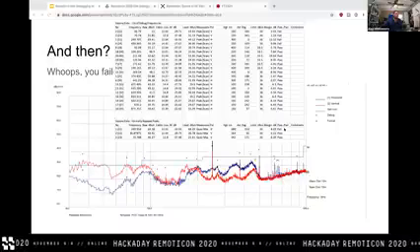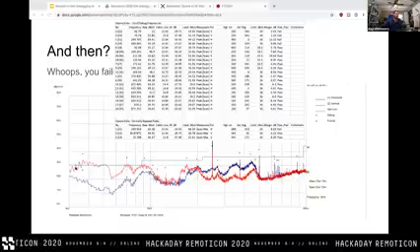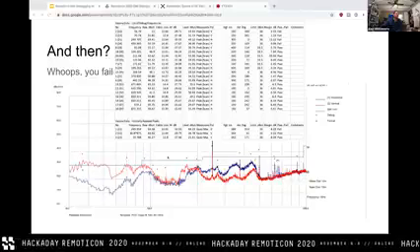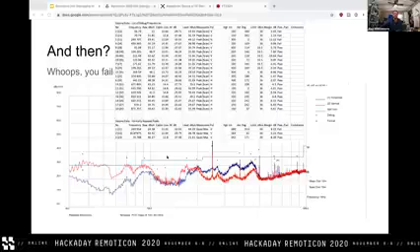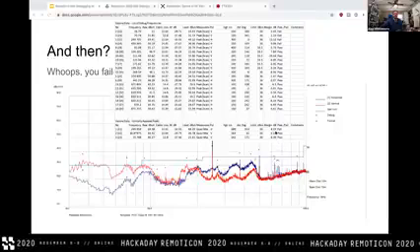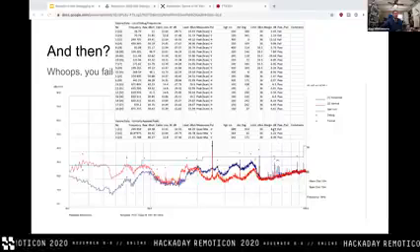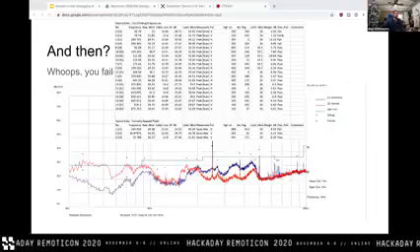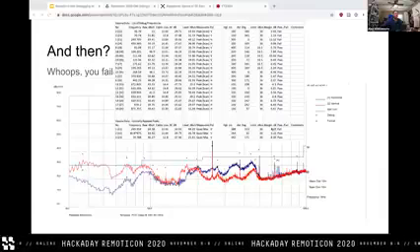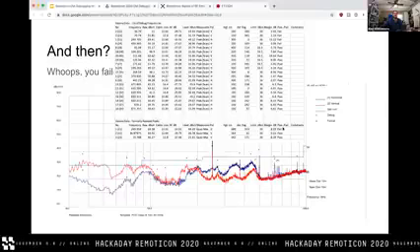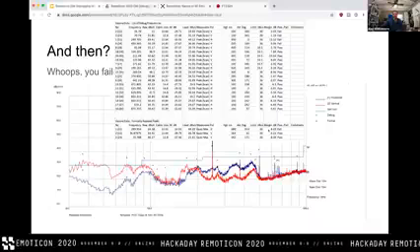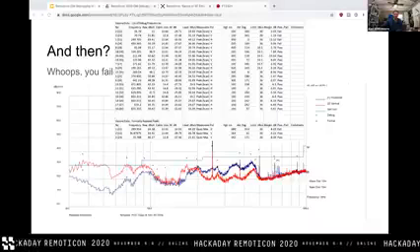For this particular product, what we see is that the peaks out here, this 36 megahertz peak, the 70 megahertz peak, and all the rest of it, those aren't actually violations from a standpoint of passing or failing the report, passing or failing the test. They're worrying because they should not be that high, and it would be good if we could bring them down below the limit line. But the only one in here that actually exceeds the limit line on a quasi-peak analysis is this 250 megahertz peak, and that's the one that we really need to focus on.